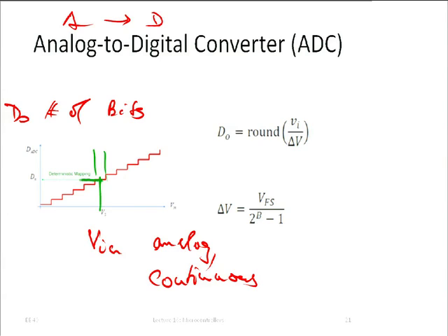Only if we make it even higher do we get the next code, right? So there is this quantization. And again, we can define the bin width here as delta V, okay? And then we can represent the quantization simply by a rounding operation. Mathematically, that's really what it's doing. Of course, there is no round statement somewhere in our circuits that does this, but that's what's happening.